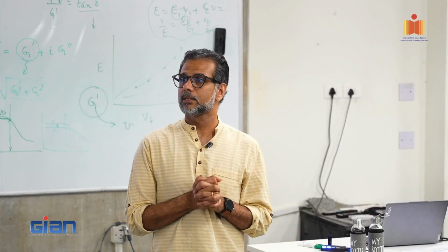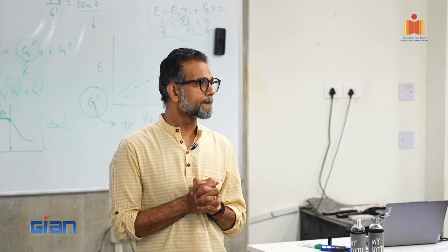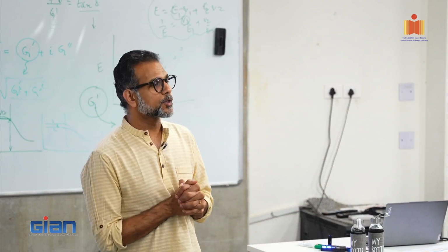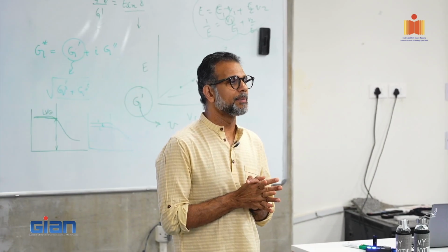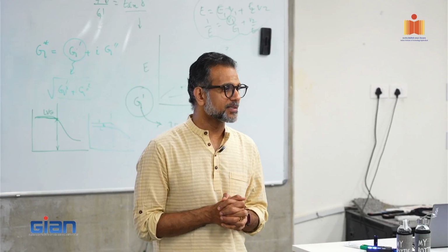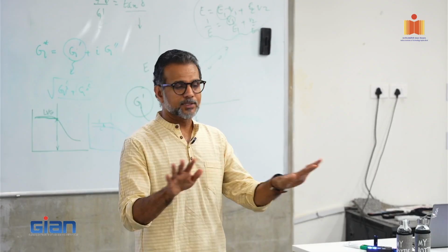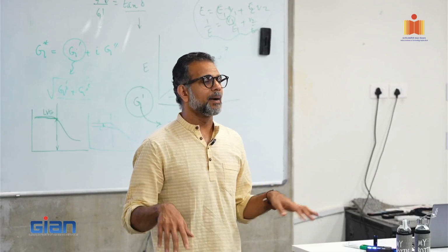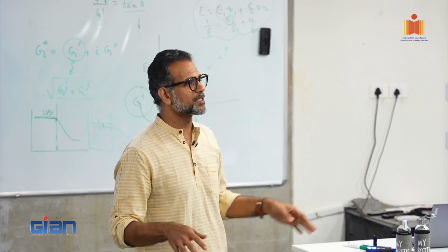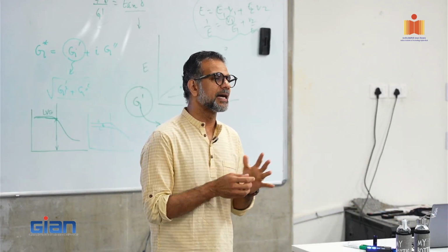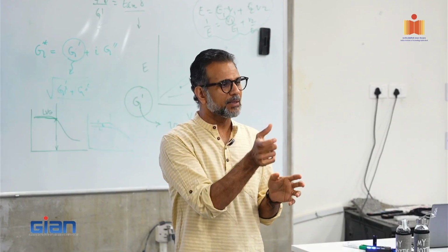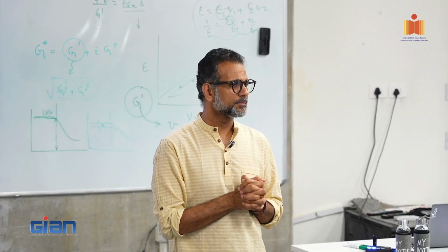Other questions? Is this more DC based or is it impedance spectroscopy? No, this is impedance spectroscopy, and we took the bulk resistance from the arc. In lots of cement-based work that we have done, bulk resistance corresponds to about 100 hertz, a direct DC-type measurement. So the bulk resistance, RB, is at about 100 hertz frequency.